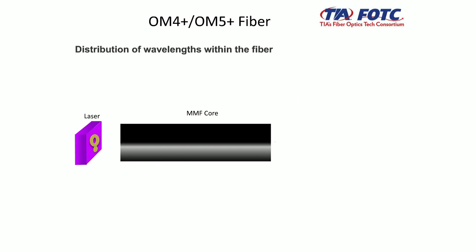So what I have here is I wanted to talk about dispersion compensated fiber. As I mentioned, there are a couple of vendors out there that are producing, like we had for OM2 fiber, we have an OM2 plus fiber. Now we have an OM4 plus fiber. So this extends the capability of OM4 fiber and basically adds more reach.